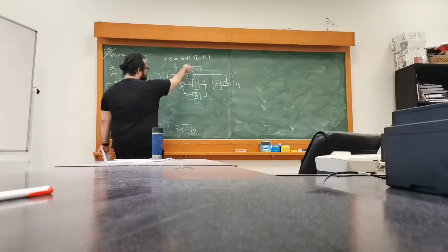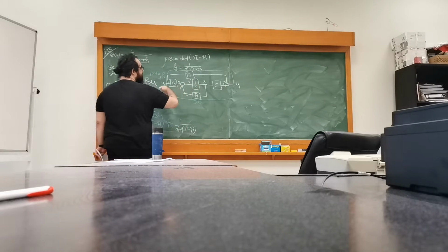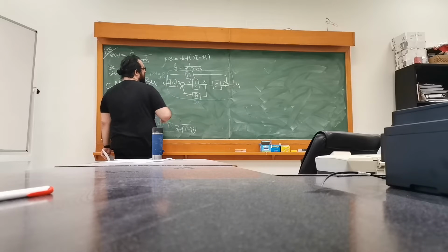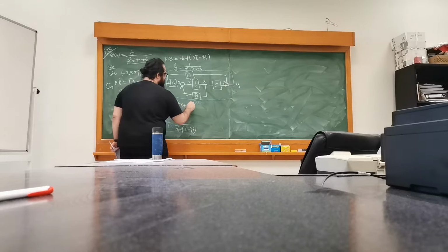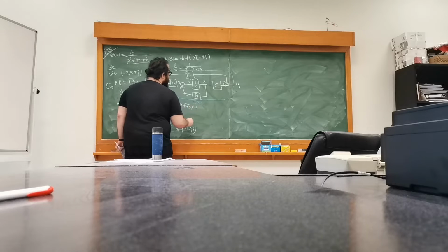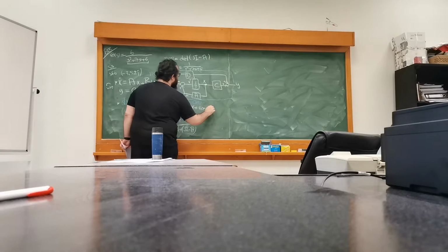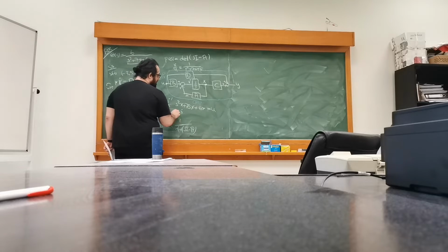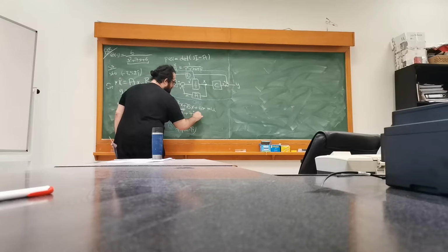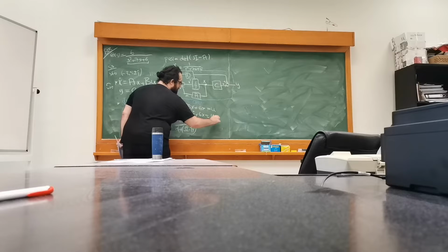And it's quite obvious to work out the differential equation or the Laplace version of this dynamic model. Namely, I cross multiply everything. So I get s squared x plus 7s x plus 6x should be equal to u. Now, take the inverse Laplace transform of this equation, and you'll end up with x double dot plus 7x dot plus 6x equals u.